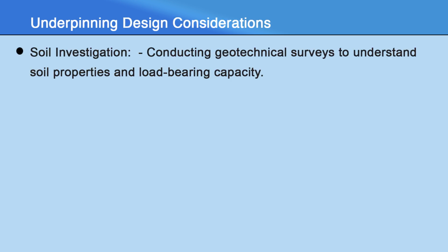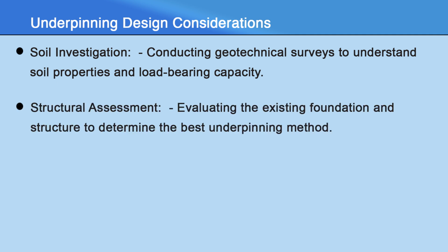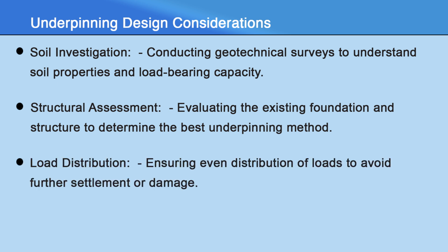These are the design considerations. First, the soil investigation, conducting the geotechnical survey to understand the soil properties and the load bearing capacity. Structure assessment, evaluating the existing foundation and the structures to determine the best underpinning method. Load distribution, ensuring the even load distribution to avoid further settlement or damage. Safety measures, implementing the safety protocol during the excavation and the construction, monitoring structural movements and addressing any issue promptly.